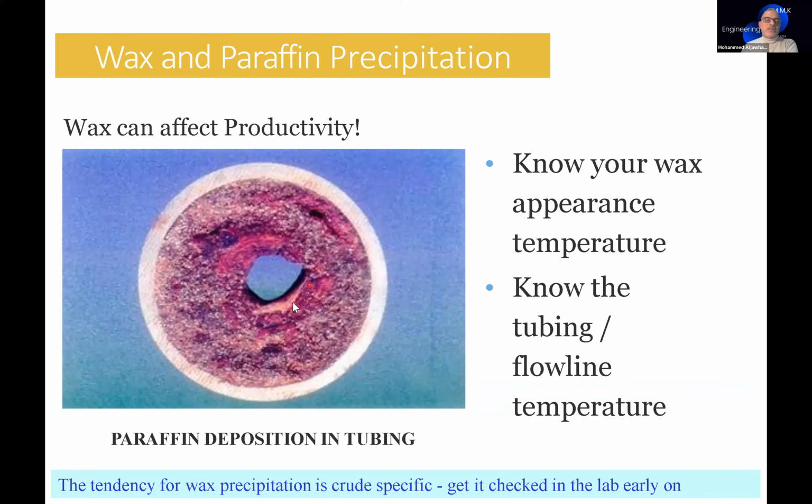For example, if the production rate is going down, why is it going down? For this kind of problem we consider the reservoir characteristics, the PVT and the chemistry of the reservoir, and I think it could be that there is wax inside, and there is evidence at the surface.